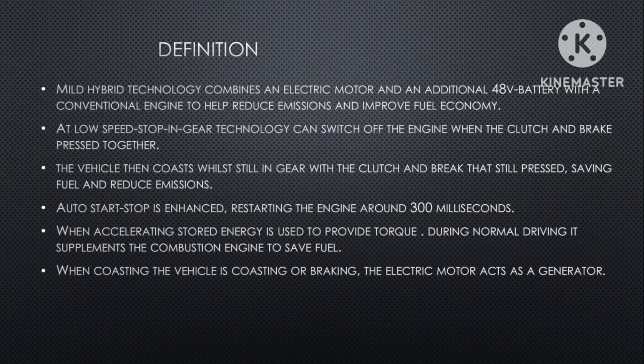At low speed, stop-in-gear technology can switch off the engine when the clutch and brake are pressed together. If the vehicle has an automatic gearbox, the clutch is not pressed manually, so we have a sensor and we have solenoids.